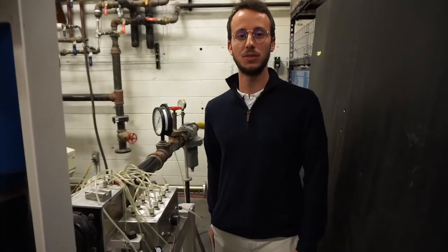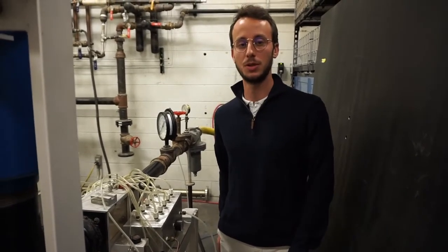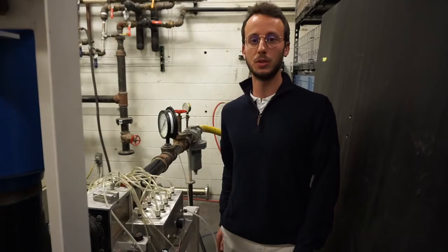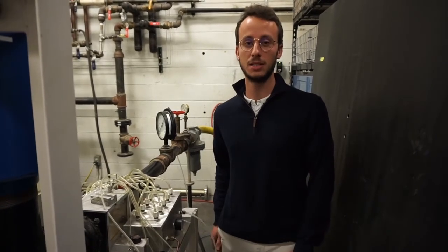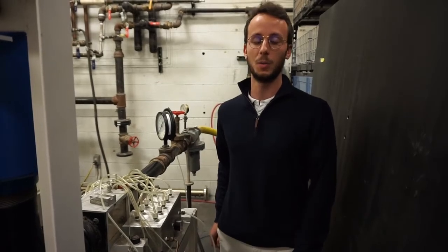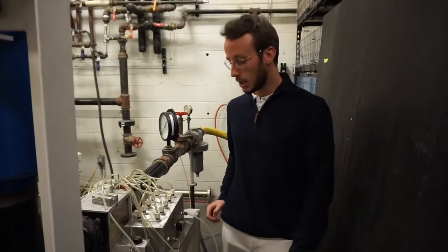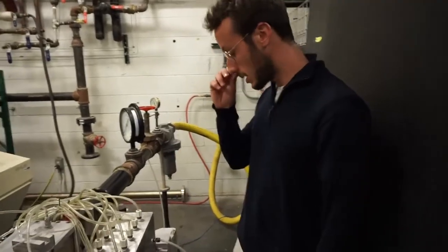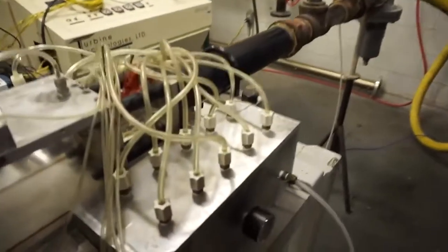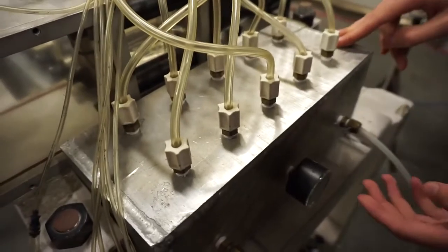You have seen in the previous video that we can see both the voltages and the pressure from the pressure transducer on the computer, but we don't perfectly trust the datasheet that we use to calculate the pressure from the voltages, so we'll use our own calibration process. The calibration process will be done using this calibration box, where we can know the pressure using this pressure gauge right here.